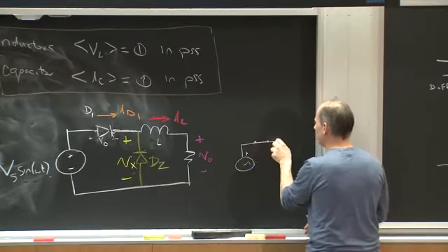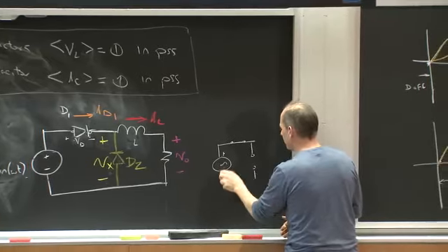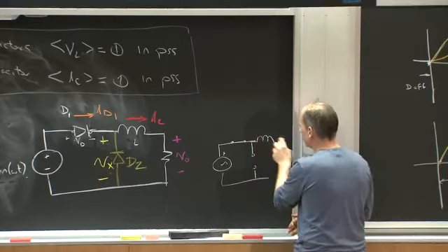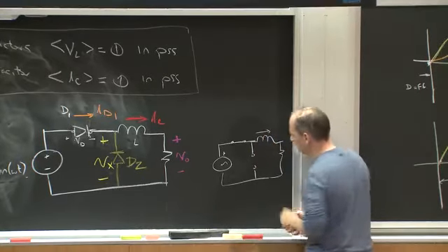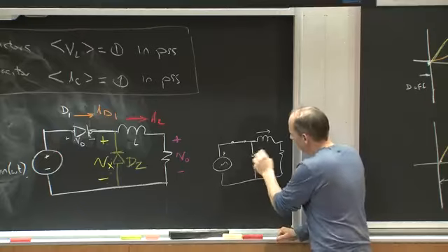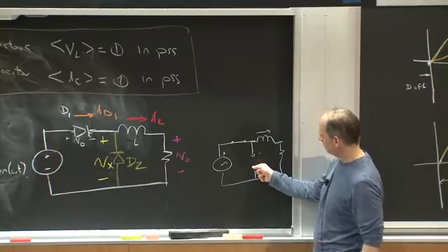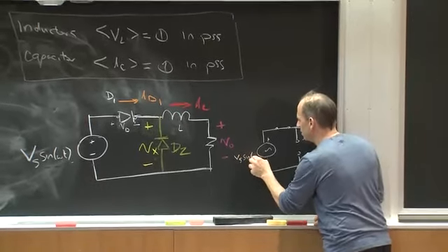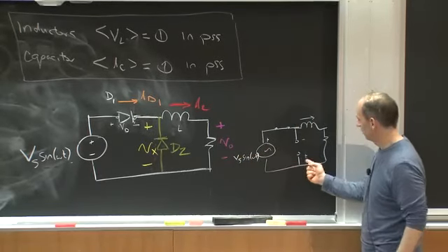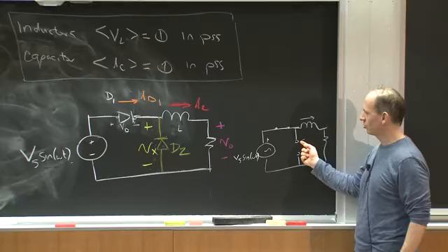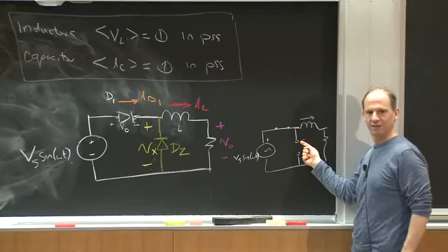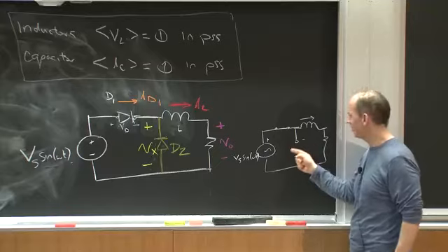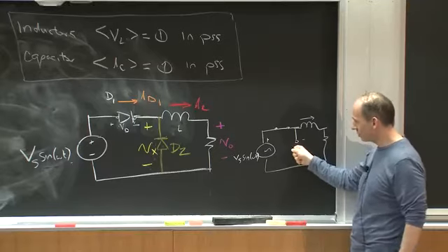I'm assuming he's on and I'm assuming he's off. And my inductor current's doing something here, right? This diode 2 voltage, if Vs sine omega t becomes negative, that means this diode voltage would become positive. Can I have a positive diode voltage? No. That means that this diode must turn on when this voltage goes to 0.